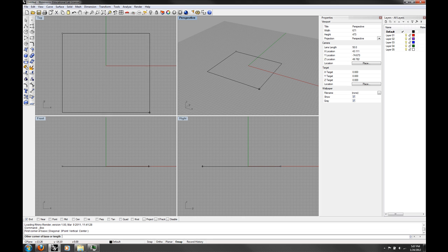And what's interesting here is if I'm in the perspective view, there's distortion, right? There's perspective distortion. It makes it hard to judge accurately the proportions of what I'm doing. But if I'm looking in the top view, you can see as I move, it updates as well. It's easier to judge if I'm making a square or a long, thin rectangle. If I'm trying to make a square, the one in the perspective viewport may not look like a square. Maybe you distort it. So you need multiple views, and you want to use the view that helps you understand what you're doing better.